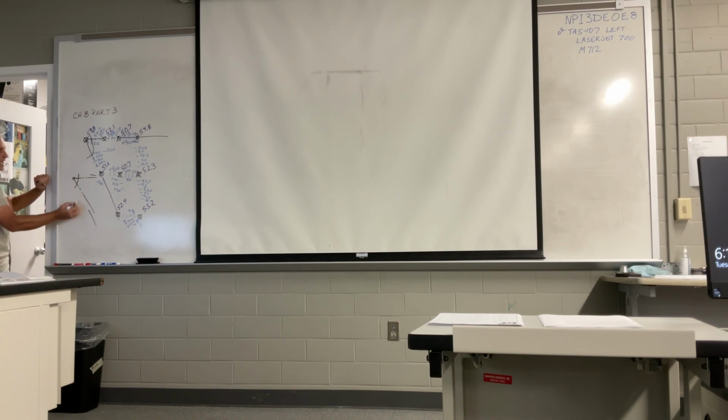Now, we didn't go outside and survey, so just like we called this point right here, even though one of these that didn't fall right on our line, we still called it a name, even though in reality that intersecting point was out there. We don't know what happens after our property, but we know that that contour does not just stop flat. There's not a cliff's edge right there. So what you're gonna do is you're gonna show that contour sticking out a little bit, then you're gonna label it. So this one right here was my 53.5. That would be all the label that I would need for that. We could clearly say, okay, what's this contour? Bam, there's my elevation right there.